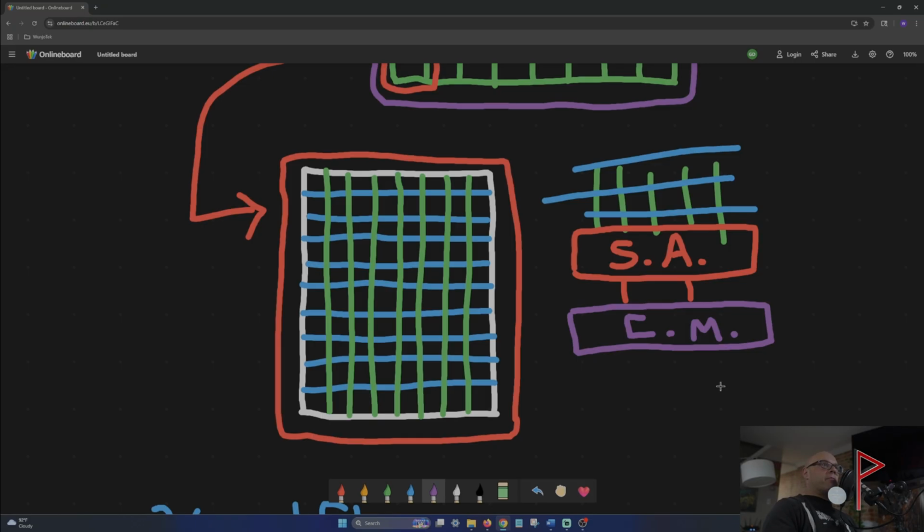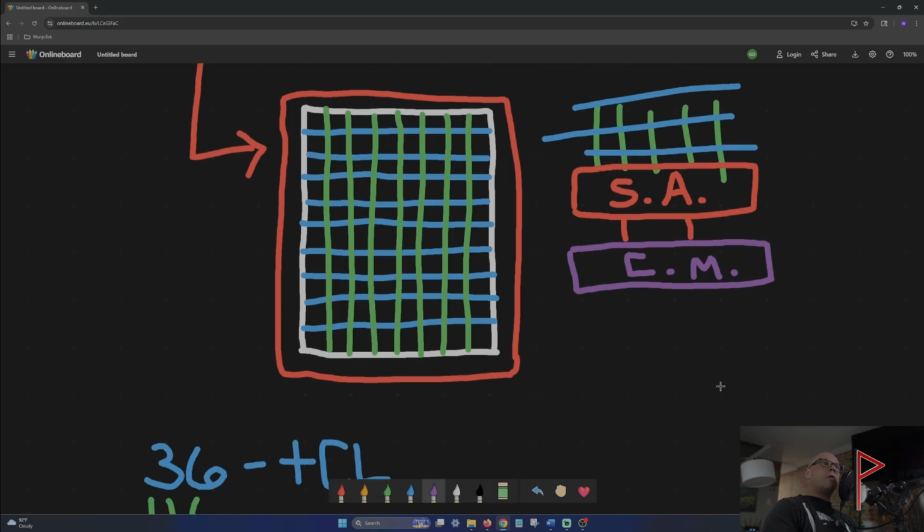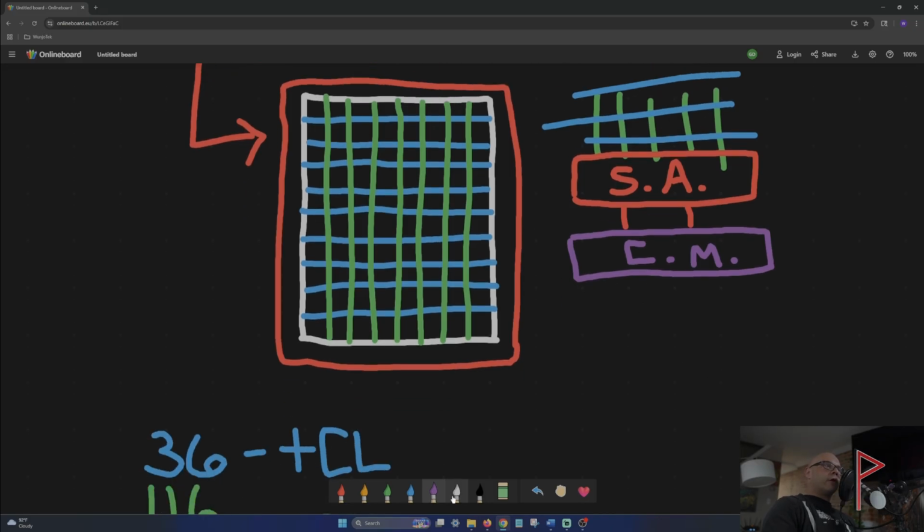And then from there, we go to your read and write drivers. So here, and this again is your 10-bit column address that tells you where the column is, and that column information is separated in 8 bits, and then it goes to your read driver or your write driver, right?